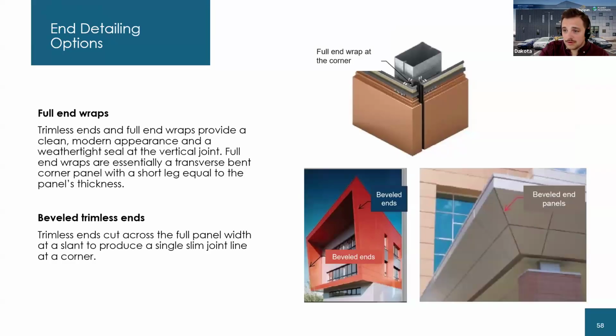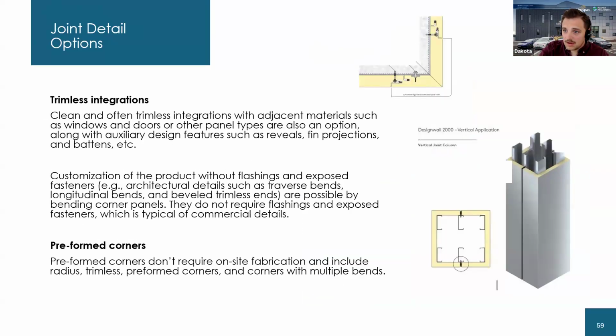As far as edges are concerned, when we think about metal, especially when it meets at a corner, we often think about trim, how that's going to look. Just know with IMPs in particular, we could take advantage of the dual nature of that steel insulation steel sandwich, right? And we can essentially miter that inside face. We have a detail of this in the next one. Can miter that inside face so that we're not disrupting this exterior steel face.